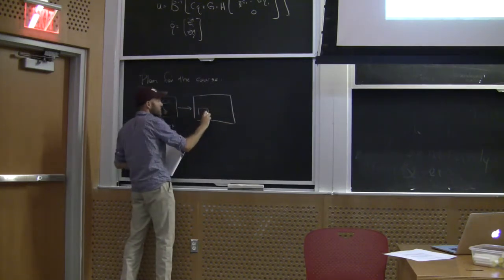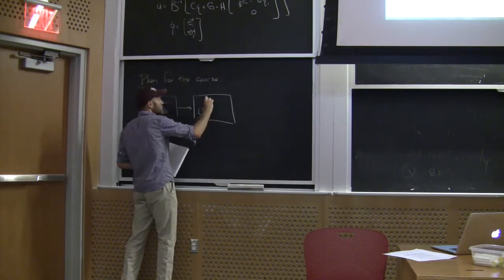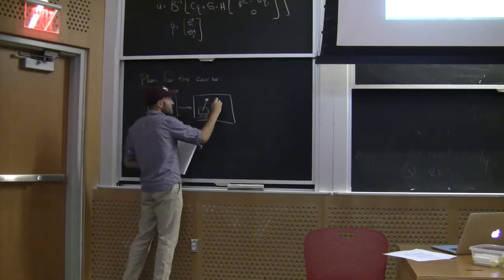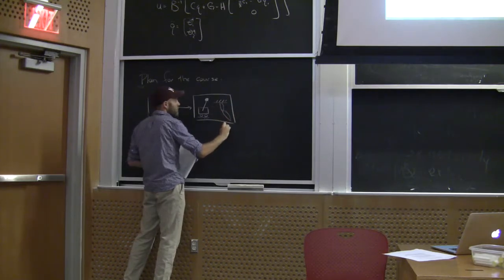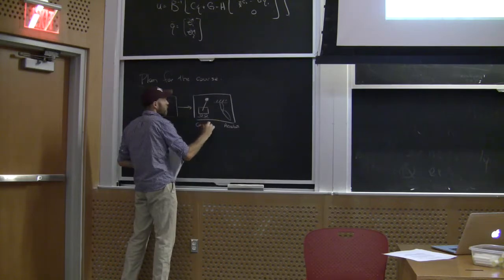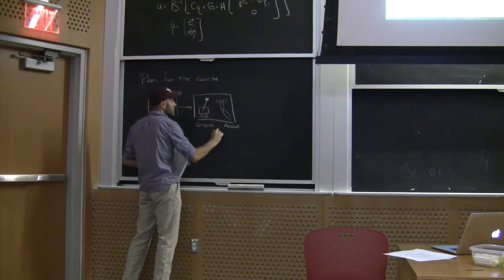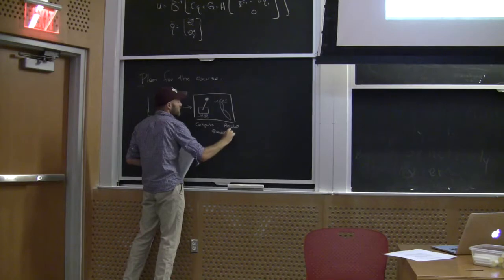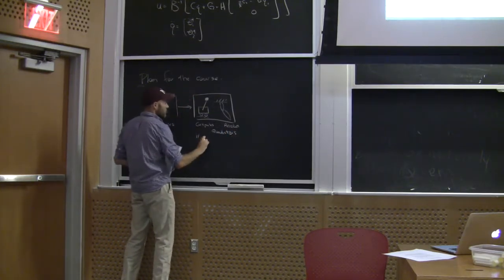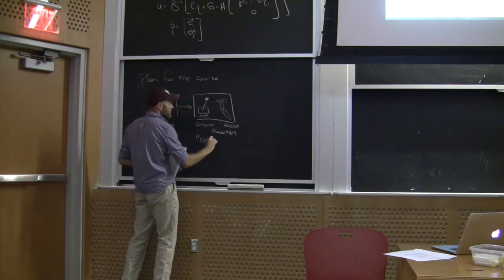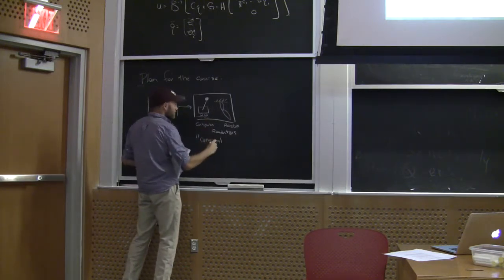underactuated systems. There's a few that you might see in any textbook, like a simple pendulum on a cart, called the cart-pole system. The double pendulum I talked about that has only an elbow actuator here is called an acrobot. Cart-pole. We'll do quadrotors then too. These are maybe the canonical underactuated systems that are missing actuators because someone left them off.